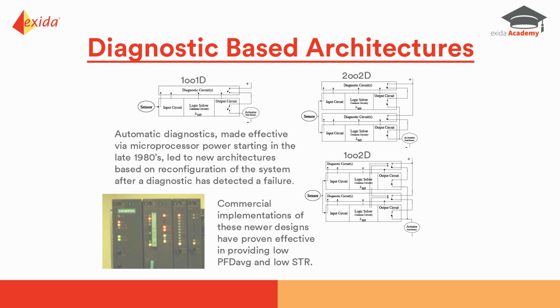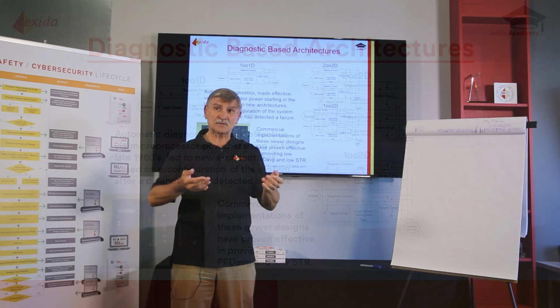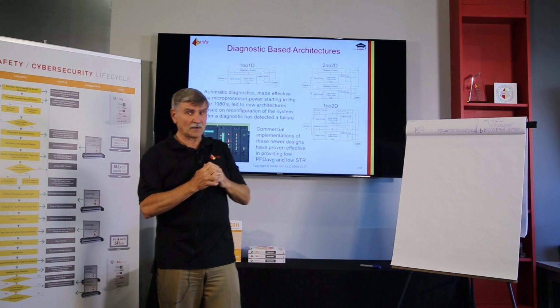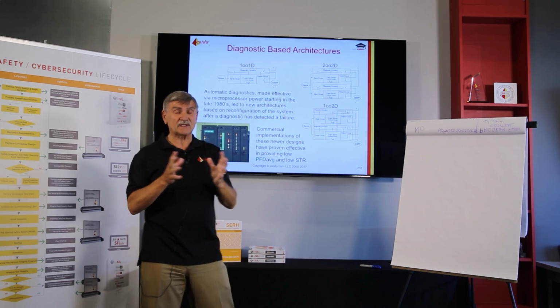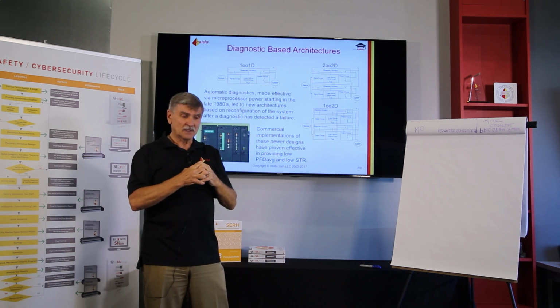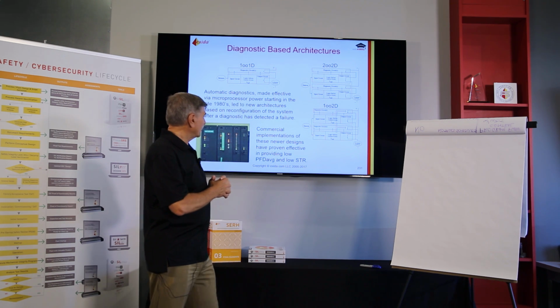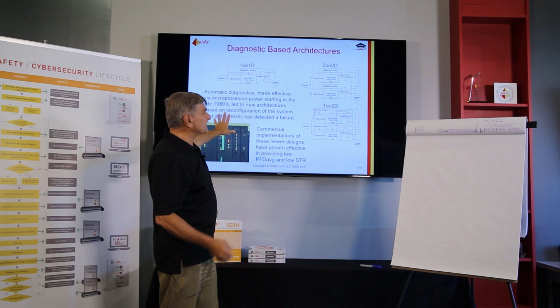As long as the pulse kept coming in the expected time period, the switch stayed closed. If the pulse went away, de-energize the output. The concept: the pulse goes away if the processor fails. And it was very strictly enforced in many safety system designs during the 70s and early 80s. We're going to take a look at these designs.